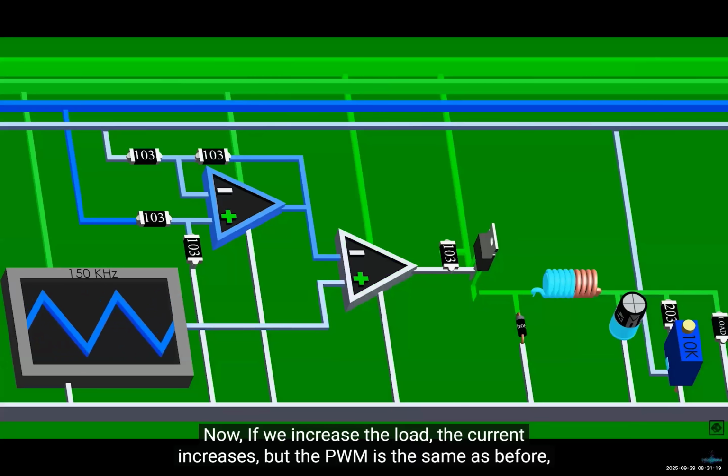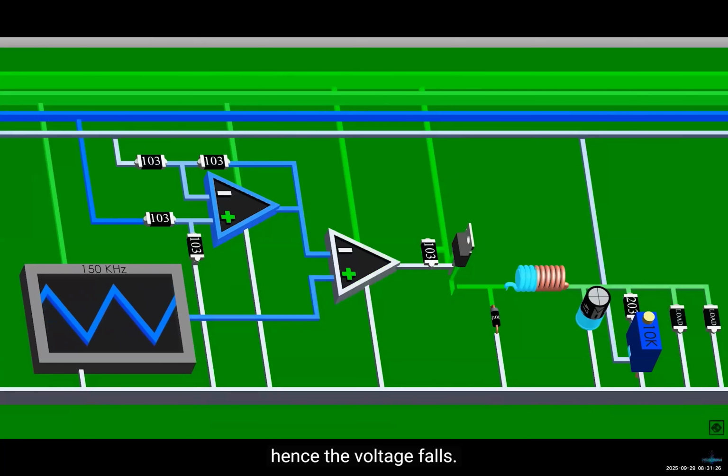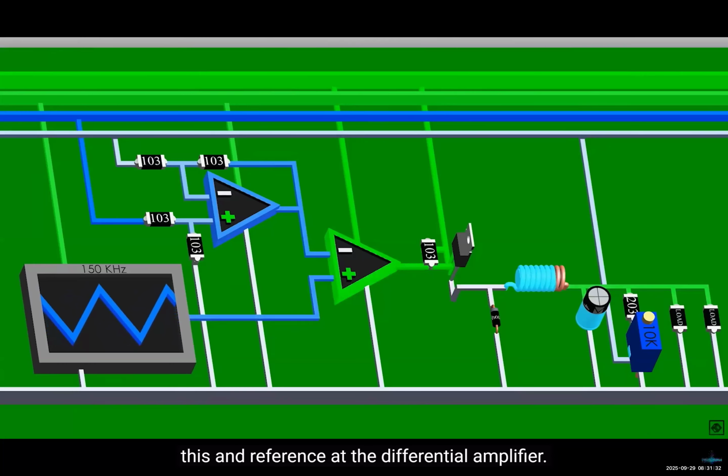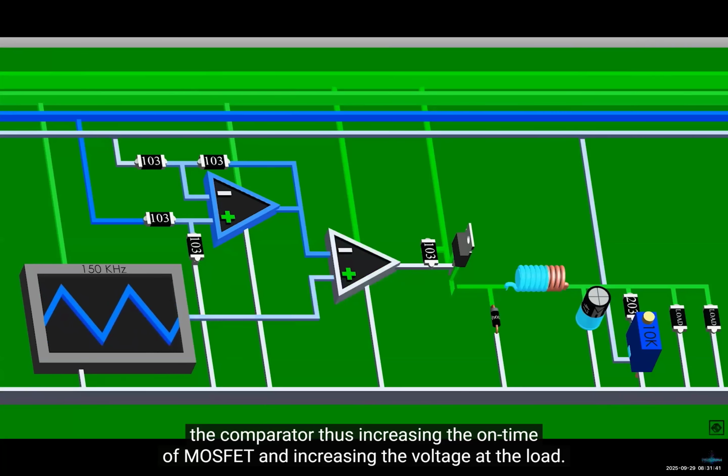Now, if we increase the load, the current increases, but the PWM is the same as before, hence the voltage falls. This causes the feedback voltage to fall, thus increasing the difference between this and the reference at the differential amplifier. This increases the voltage at the output, and then the duty cycle of the PWM from the comparator decreases, thus increasing the on-time of the MOSFET and increasing the voltage at the load.